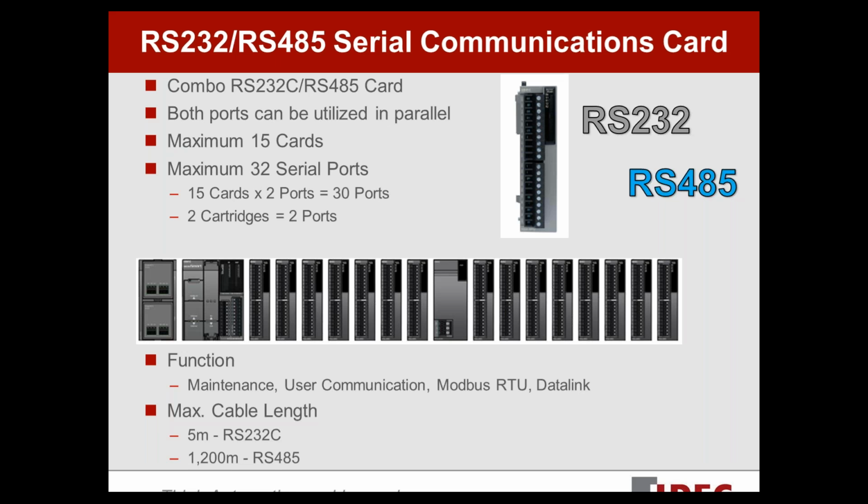We also have a serial communications card. Now, this plugs in just like an IO card. Okay. Each card can use RS-232 communications and or RS-485 communications. The reason I say that is each card has 2 serial ports on it, and either port can be configured as RS-232 or RS-485, or you can do one of each. That's fine. You can do a maximum of 15 of these cards in a total system.